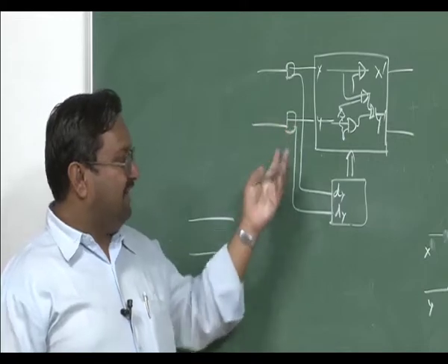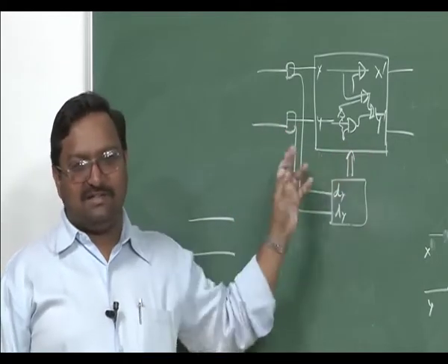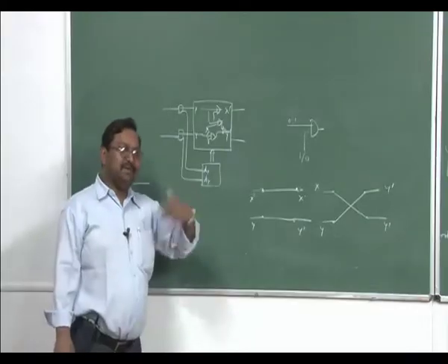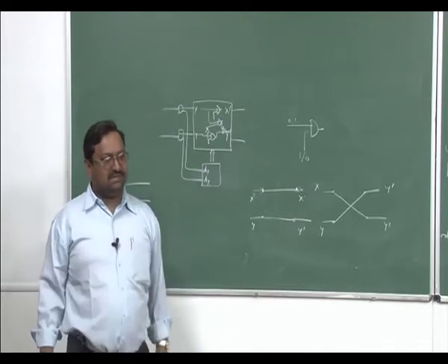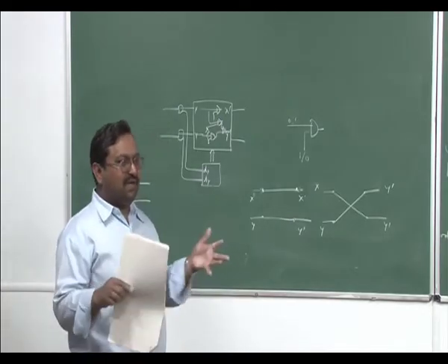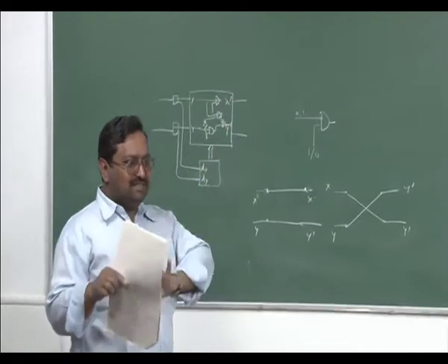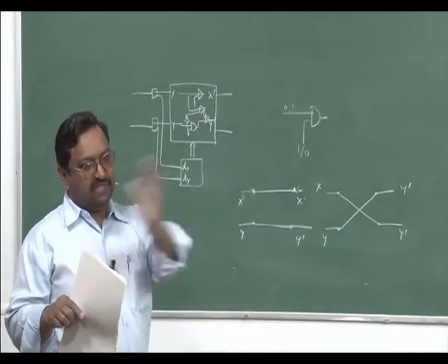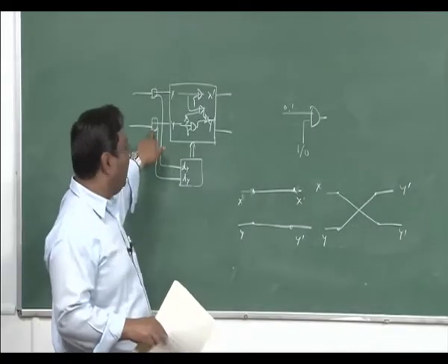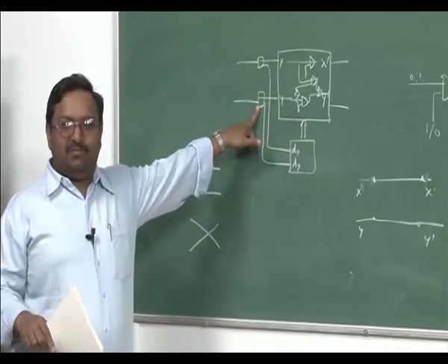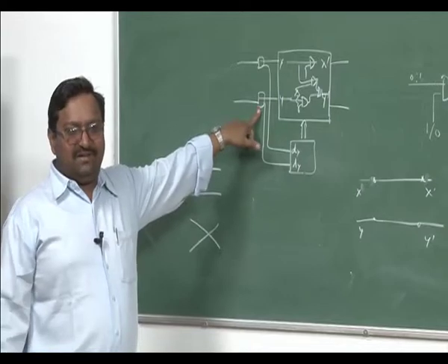So it has to be received, analyzed and then retransmitted again by this interface board. You have to repeat it multiple times in the switch. It is not like a crossbar, where only the interface board does the analysis, then internally you just set the cross points and things pass through. No, you require basically all clock recovery, putting into memory, analyzing everything at this point.